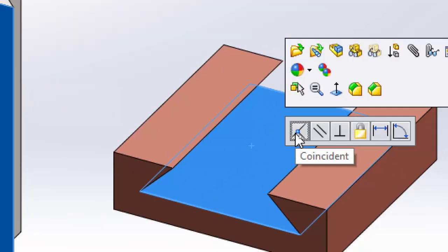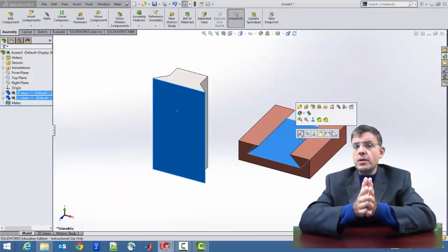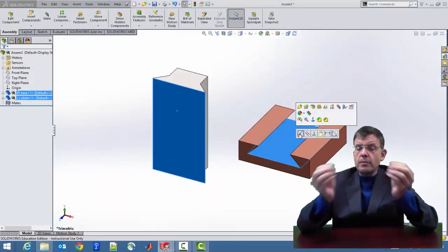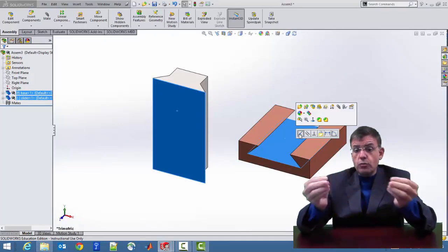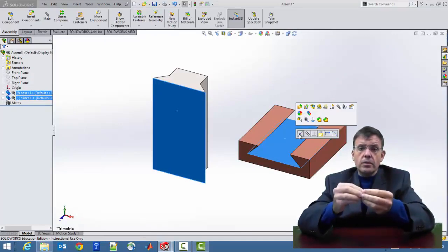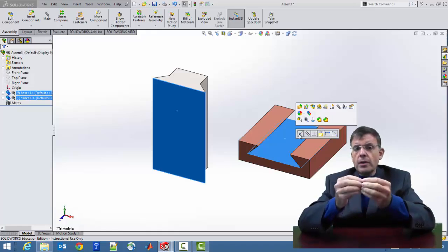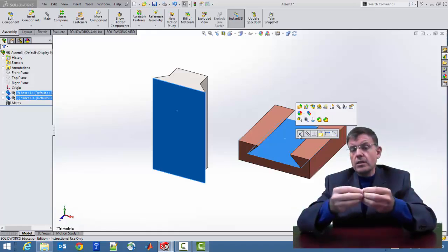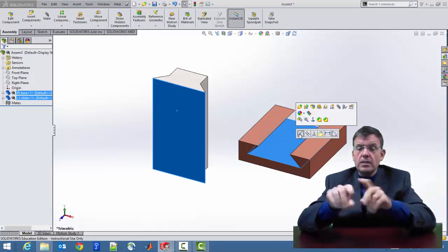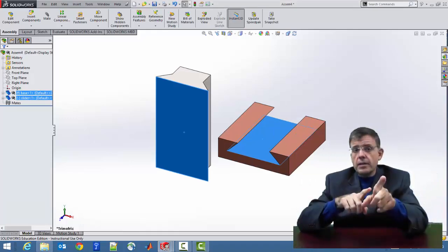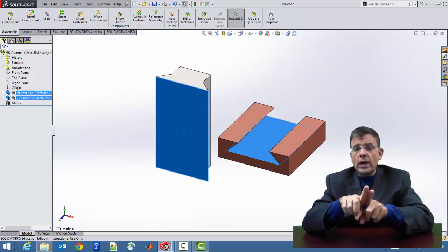Now, of course, when we talk about coincident in there, just to clarify a little bit of the terminology: if we're talking about coincident points, okay, that's one point literally on top of another. When we talk about coincidence in the context of lines or edges, that just means collinear. Collinearity doesn't imply that one starts at the same point as the other.